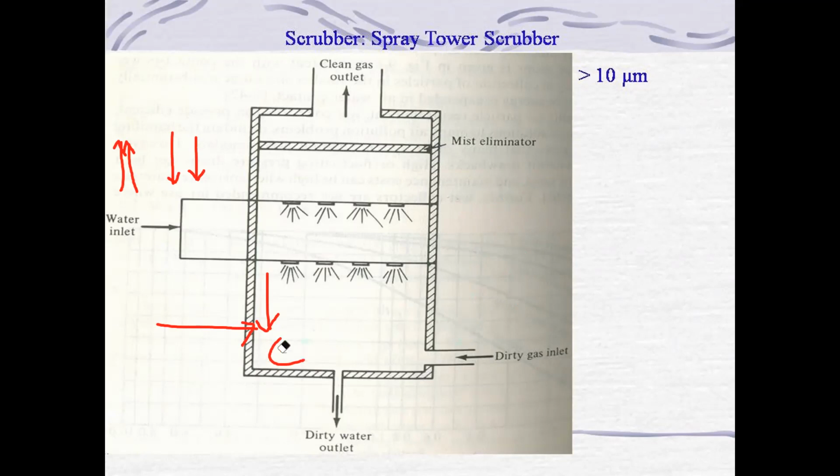In a scrubber, very fine particulate matter also gets scrubbed down, as well as the polluted gases, dropping at the bottom. From the bottom, you can remove these impurities. And here is the mist eliminator. What is the role of the mist eliminator? When the liquid is used for scrubbing, we have converted it into fine particles. And sometimes, because of the blowing of air in an upward direction, some particles keep blowing along with the water.